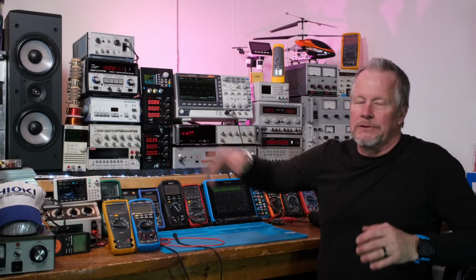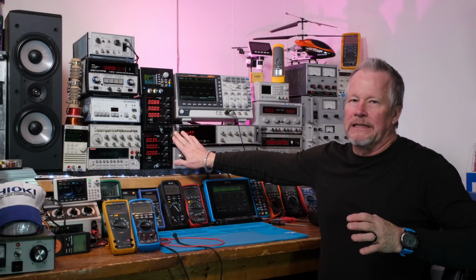All right, so then that green wire, and ground is usually a green wire, a lot of times with a yellow stripe, sometimes solid bare wire. But that wire goes to all your receptacles and ties all your equipment, anything with a metal housing, let's say. Anything with a metal housing and 3 prongs is going to take that third prong, that green ground prong, and tie that chassis to earth ground.